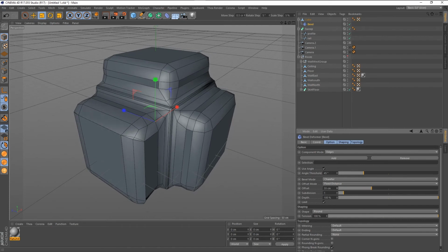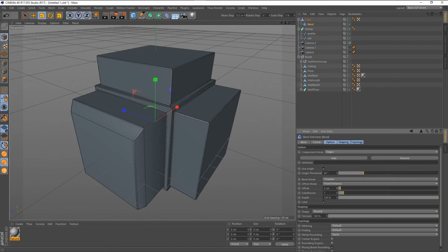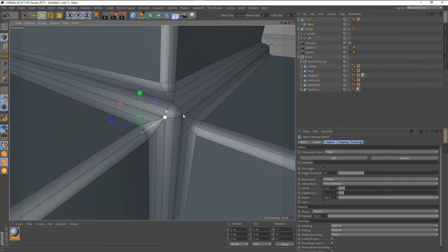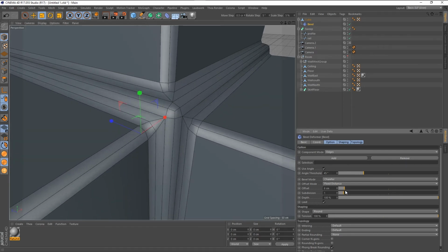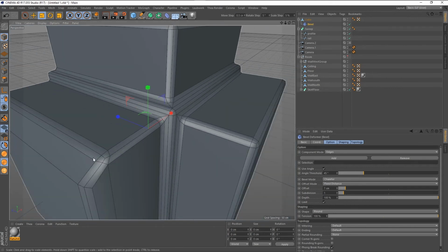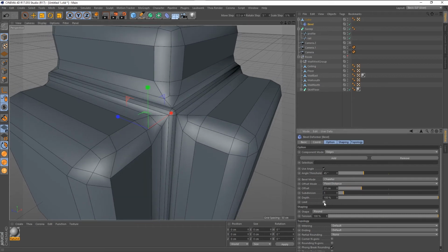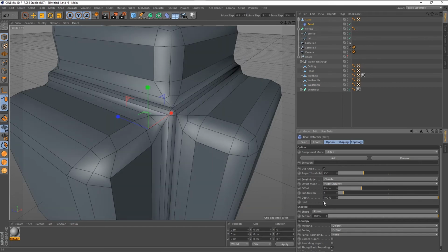I actually like the way this bevel limit works better than the Blender limit. The Blender bevel limit kind of just stops you from beveling, and you can't bevel anymore. But here I can keep expanding, and you're noticing right in here, when it reaches the limit and can't bevel anymore right there, it'll still let me bevel out here and out here even more. I can keep going. So that's kind of nice. So that's what the limit does. If you don't have a limit, then the bevel goes through itself, and that doesn't look good.